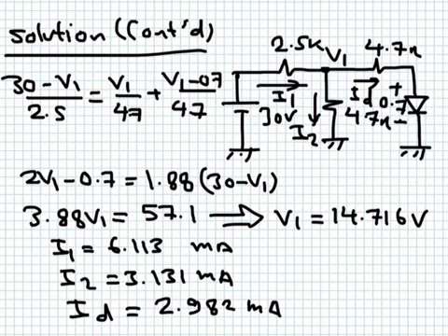So now we assume that the diode is on. So I have a current. There will be a current flowing everywhere in the circuit: a current I1 here, a current I2 here, a current ID here. Then this is a typical circuit with two loops and with one node, so we can apply nodal analysis. Nodal analysis is the easiest way of solving this circuit.